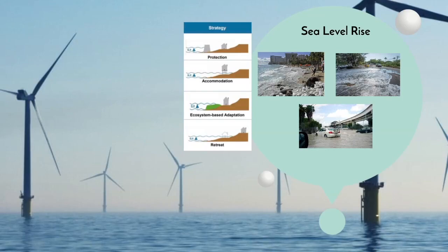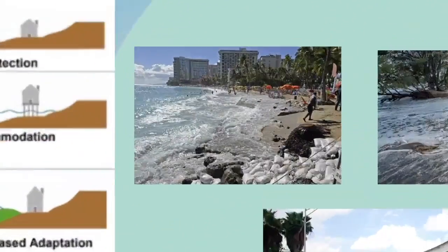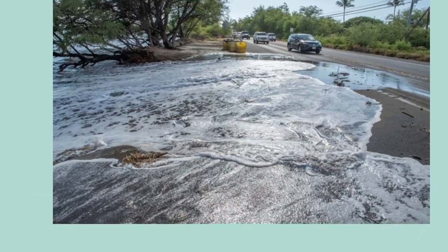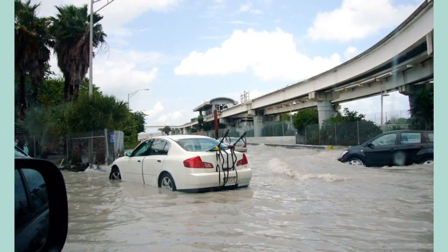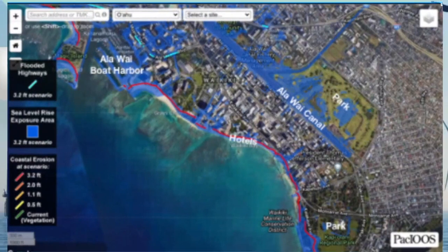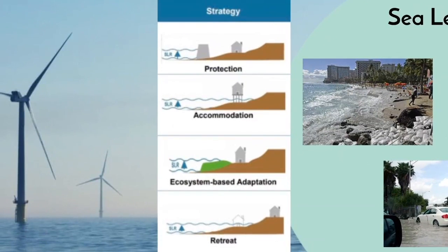Sea level rise generally impacts different areas in three different ways: coastal erosion, high wave damage, and inundation or flooding that may impact areas more inland. A vulnerability assessment is done to identify and prioritize communities or areas most at risk to one or more of these threats. Then a plan is created using one or more of these four different types of sea level rise adaptation strategies.